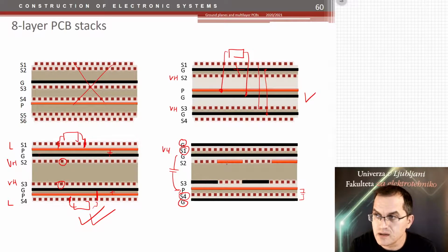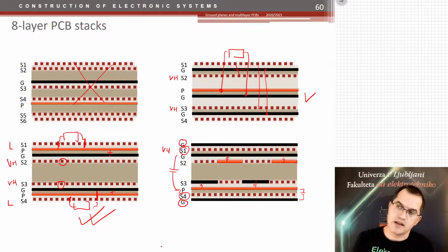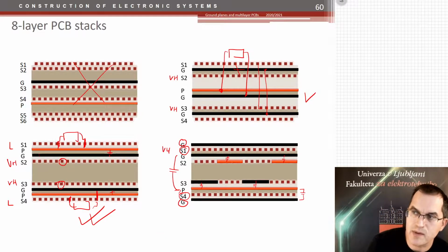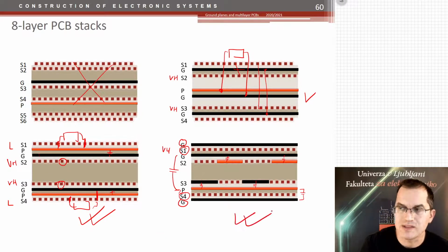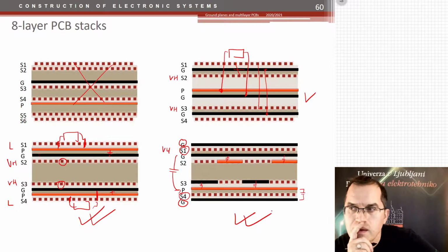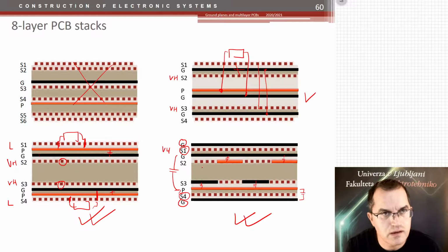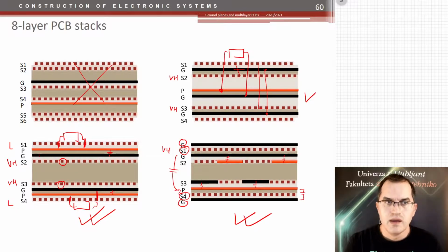Because now if I put them interleaved in the way that the capacitances here do not interfere with the rest of the tracks, then I might get a much better option. So that would maybe be then a good PCB. But only if I really utilize the ground and power planes in the mid layer. Alright, what else?